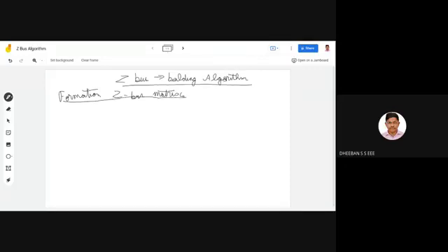You know how to form the Z bus matrix. For example, if they have given an admittance matrix, you'll take the reciprocal, the determinant value, and do those calculations. That is, to be short, you'll be finding the inverse. But now we are speaking about the bus building algorithm, that too with respect to your Z bus.